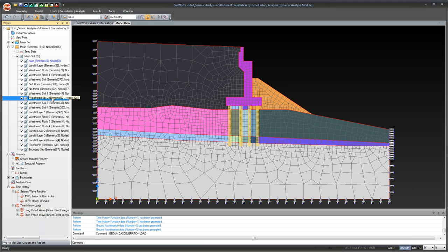If you have a model that's giving you some issues, it's always a good rule of thumb to go back and check over all of your properties, or excuse me, all of your elements, just to make sure that all of them are assigned, because that's where a lot of failed analyses or errors come up: you have something assigned but it's not actively in use.